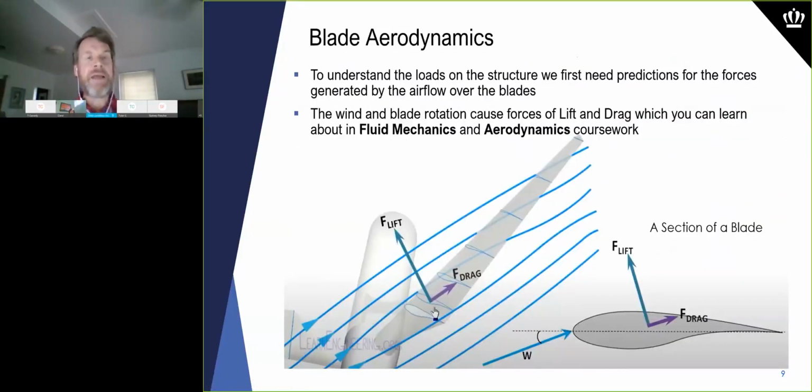All right, let's focus on blade aerodynamics for a second here. So here we're looking down on the turbine. This is the axis of rotation of the turbine. We can see a turbine blade, or one of these wing-like devices that's sticking out. And we think about the design of the actual blade. It looks exactly like a wing, except that it's twisted as we move away from the hub out to the tip. So much like a propeller, if you've looked at a propeller before.